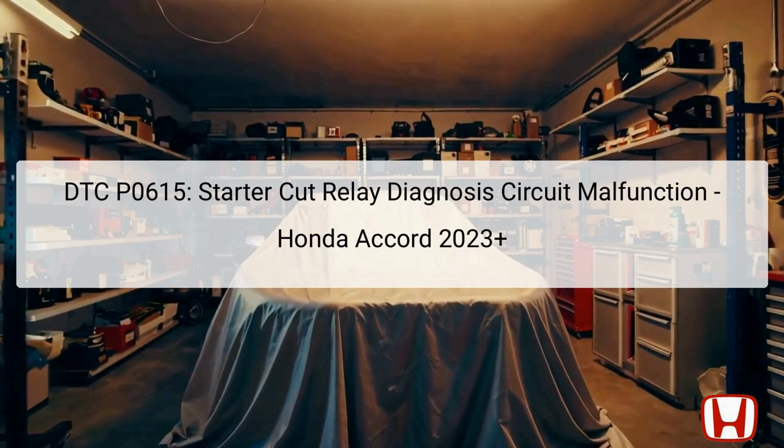The diagnostic trouble code P0615 indicates a malfunction in the starter cut relay diagnosis circuit. This malfunction is typically detected by the powertrain control module, PCM, when it identifies an abnormality while monitoring the starter cut relay input voltage. The starter cut relay plays a crucial role in the vehicle's starting process, ensuring that power is effectively routed to the starter motor when required.